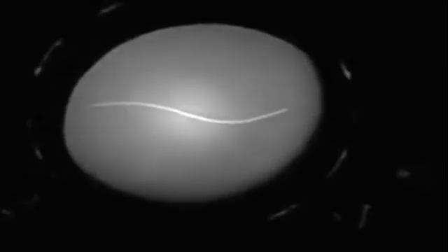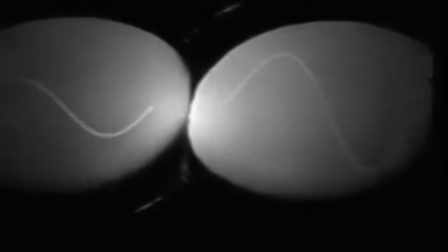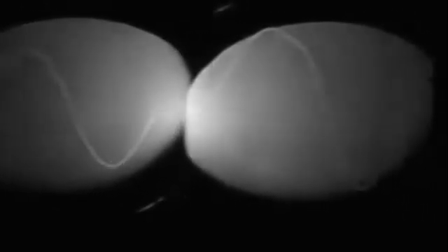Here is the waveform of the original audio signal. Compare it with the waveform taken off the first stage. In spite of the increase in amplitude, there's little distortion at this point. Here is the comparison of the first stage with the second stage output. Here is the pattern of the third stage. Comparison of the waveform at this stage with the previous one shows distortion.